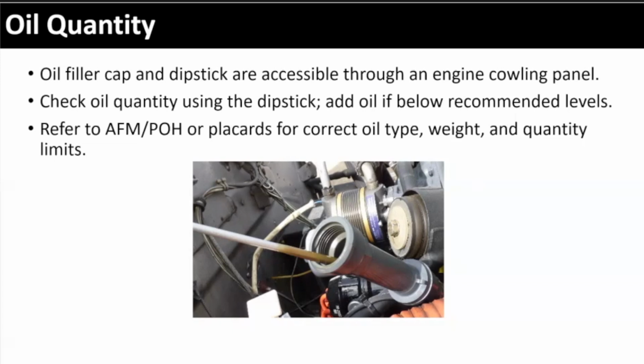To your point, overfilling it, especially when you have new oil, can lead to problems too. I actually did that. I couldn't see it, and I pulled out the dipstick and it looked like there was nothing in there. So I started adding a quart. Next thing you know, it's running out the top and started smoking, because I put too much in. So I shut it down. Luckily I drained enough out of it that it wasn't damaged. So it can be difficult.